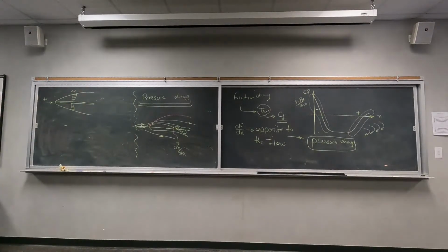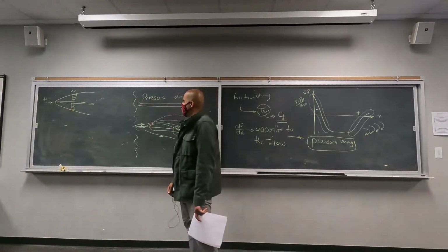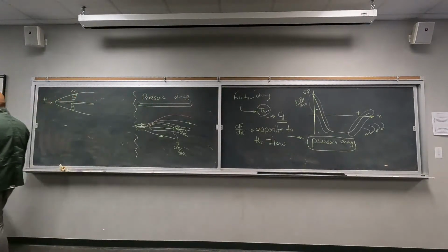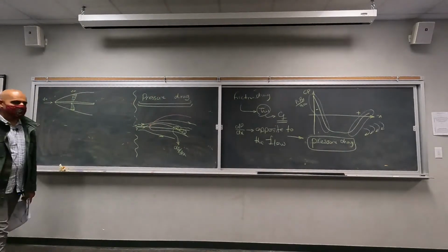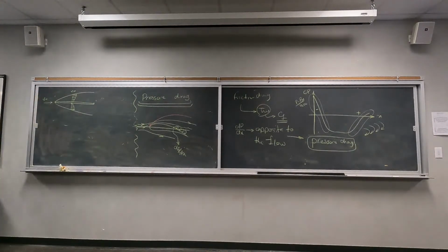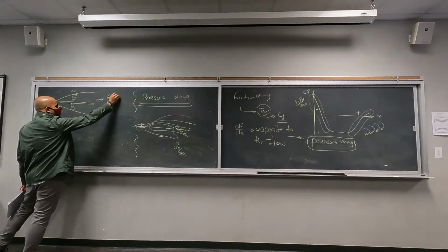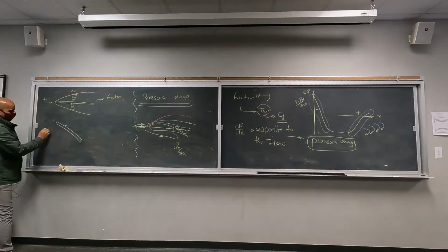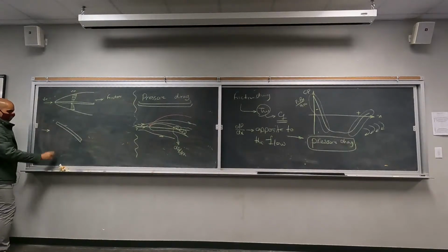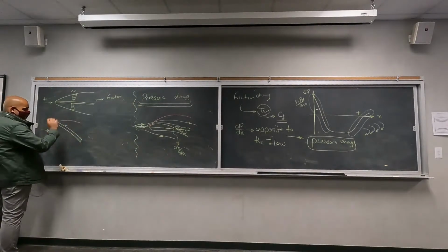This effectively happens because some of the fluid momentum is going to be lost because of the presence of the flat plate, right? This momentum usually dissipates as heat, or any other kind of energy dissipation mechanism. So that is going to be the source of friction drag. But let's say your flow is approaching at an angle. You will definitely get the boundary layer, right? But because of the adverse pressure gradient, at some point,